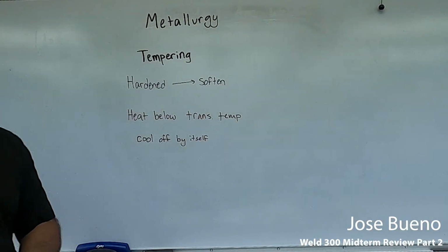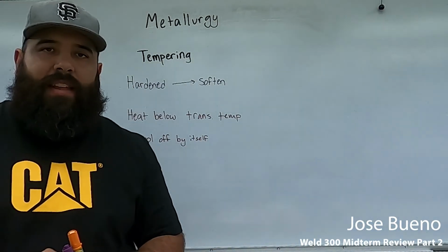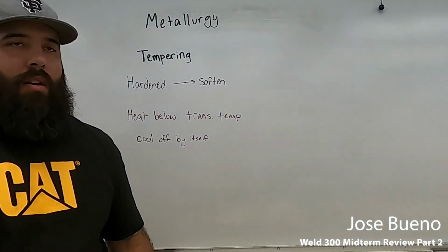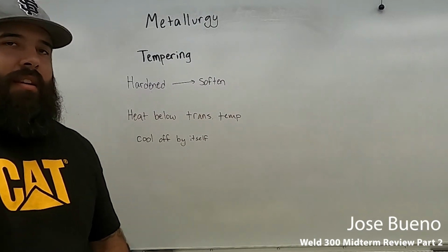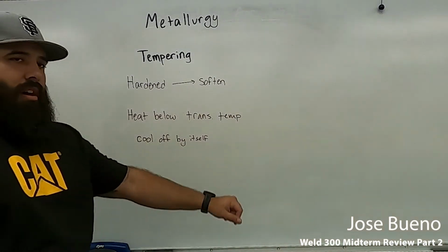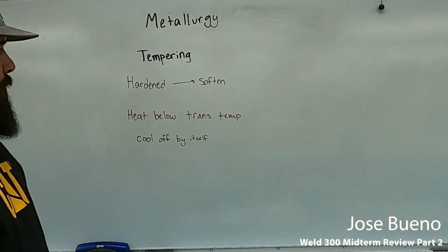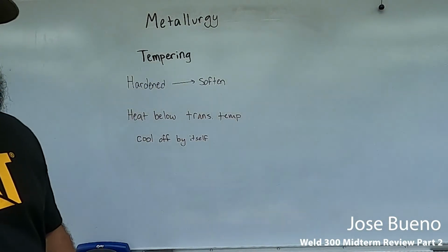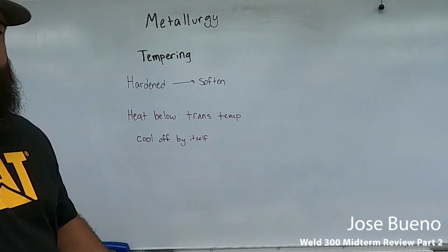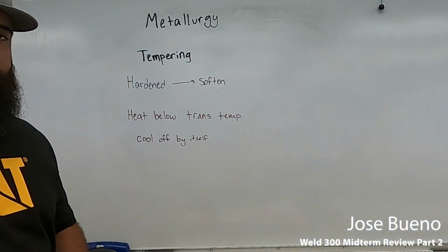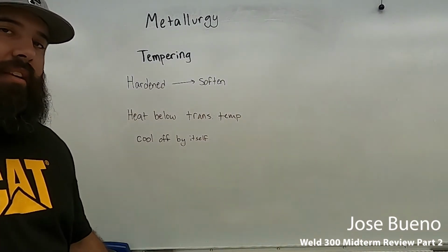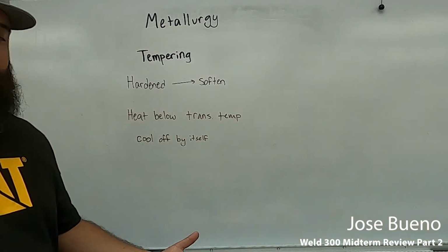So this means we're not setting it in front of a fan that's pumping out air or cold air. We're not dunking it in the water. We're not setting it in sand. We're allowing it to cool off by itself. So what this does is it decreases brittleness, it slightly decreases hardness, only to the point where you're increasing strength and ductility, but mainly ductility.